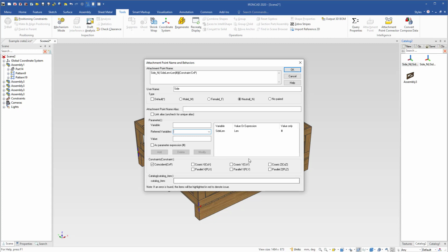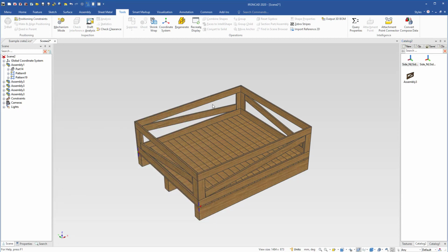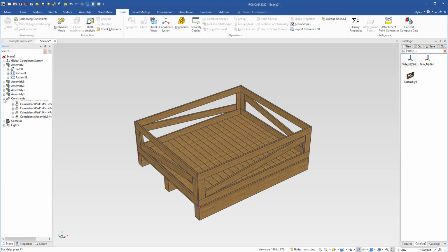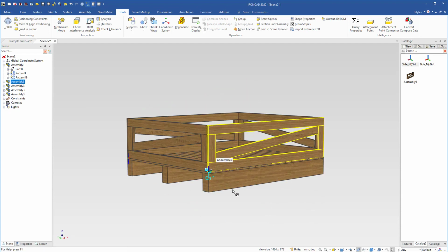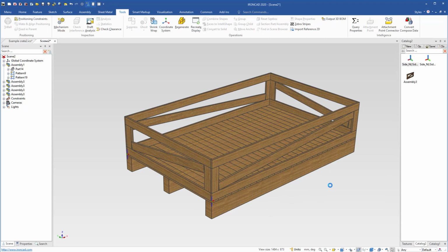Then you can get into advanced things by building the constraints so that when this moves, all these elements move and adjust and build a physical constraint. If you look in our scene browser, there is an actual physical constraint built there on the fly for us. You can also do some other advanced things here that we didn't show, which is actually searching for a catalog. If you had an element inside of here, you can drag and drop and search for a specific catalog element to connect to. Anyways, you can see here, these are the constraints I was referring to. It automatically built those constraints on the fly as it was being dropped out. There's a constraint element from each one of these being applied, which gives us the behavior when it adjusts, so it knows how to move properly and adjust.